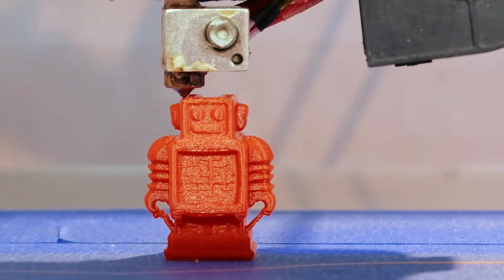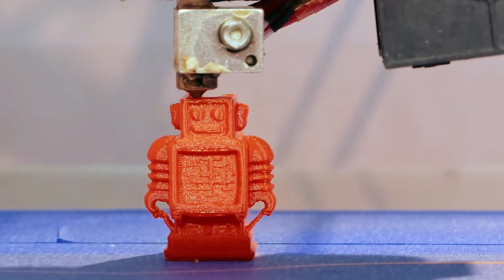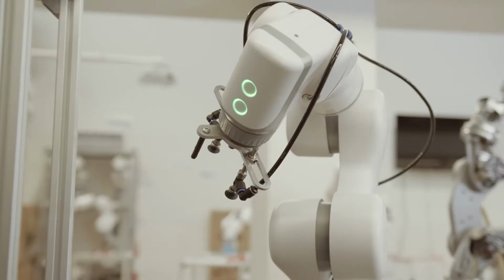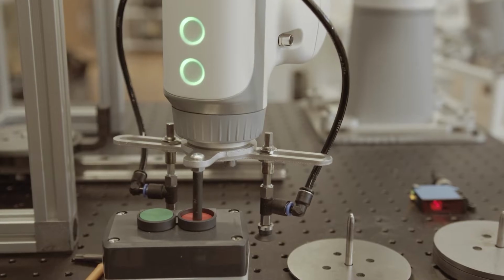Obviously, I don't know what 3D printer I'm going to use to print this, so I cannot take the exact tolerance into account. Some have bigger tolerances, some have smaller tolerances. Since this pocket doesn't have to be micro accurate, it's not a heart valve or anything like a rocket piece, it has to be rough, so I can go for a bigger size, making sure even if the manufacturing tolerance makes it slightly smaller, the light can still fit into this pocket.